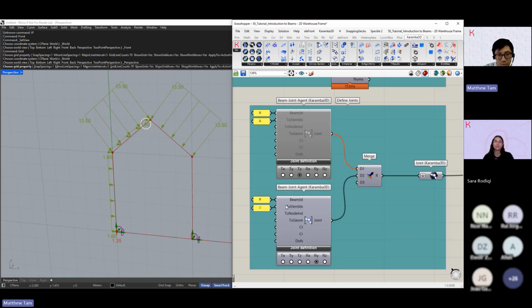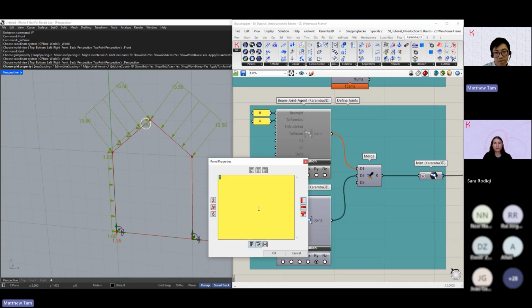So in this case, we want to say that the B beam, for example, the second one here, has a joint condition when it connects to C, which is this one. So essentially at the pitch, we have a release. And this release is the Ry, and that's why you see this circle there. If you were to say, for example, at A, you can specify it by writing A, and you'll see that the joint is there.